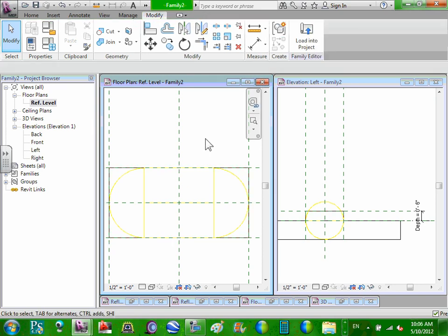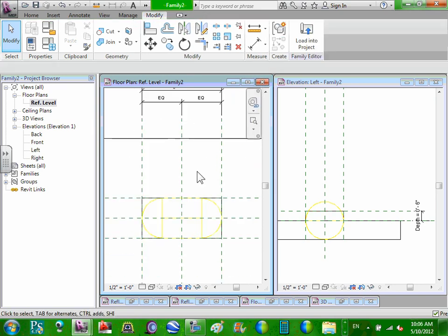One other thing that we would probably do with this, but you don't have to, is create a symbol over the top of this. If your symbol is something that doesn't represent the geometry at all, meaning the receptacle has nothing to do with the box, it's just out of the blue, a circle with two lines, that would be a generic annotation family that you'd create and then load into this and then place. If it's a 2x4 where the symbol actually does match what's going on, you would create a detail item, a detail component family that you would nest into this project.